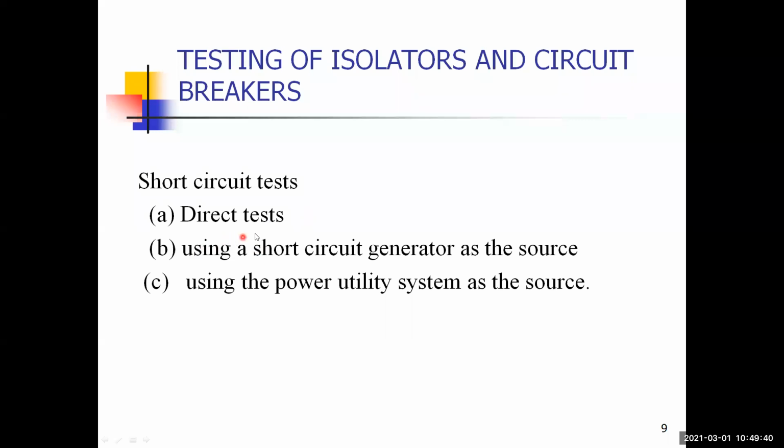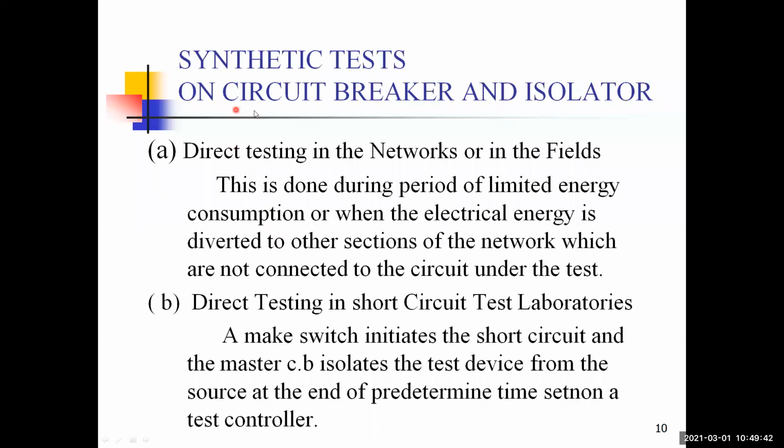Under the dielectric test also. Next, a synthetic test on circuit breakers and isolators. There is direct testing on the networks or in the field, and the second one is direct testing in short circuit test laboratories. This is done during a period of limited energy consumption, or when the electrical energy is diverted to other sections of the network which are not connected to the circuit under test. So this is the synthetic test on circuit breakers and isolators.